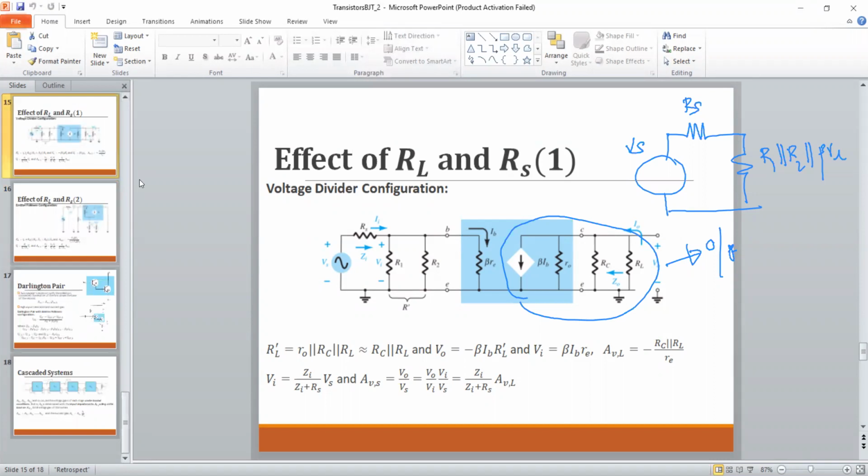For the exam, you will get a very simple transistor configuration. You should be able to draw the AC equivalent circuit and evaluate the corresponding parameters. Most probably you will be asked to evaluate the input and output impedances, the voltage gain, and discuss what the output would be. Because in most cases you will get a minus sign in front of this gain, you should be able to draw the input and output variation.